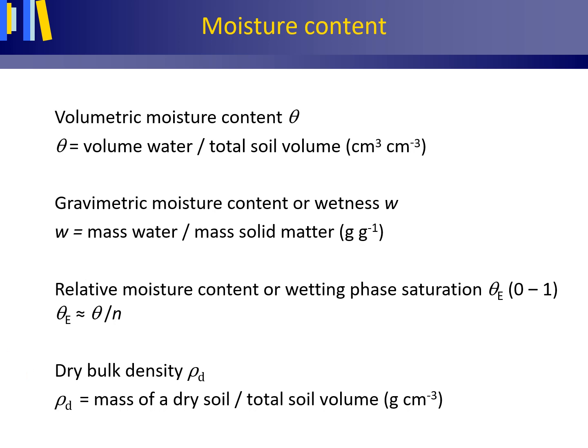Further to this, for the GO4 4417 students, the density of the solid fraction of a soil is defined as the mass of solids divided by the volume of solids. For a typical mineral soil, this density of the solid fraction can be taken as 2.65 gram per cubic centimeter. This is close to the density of quartz, generally the most prevalent mineral in the coarse fraction of a mineral soil.